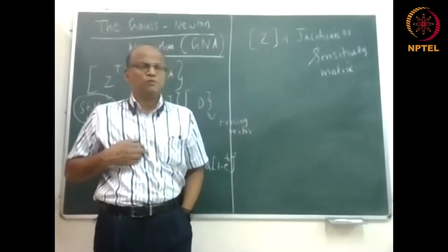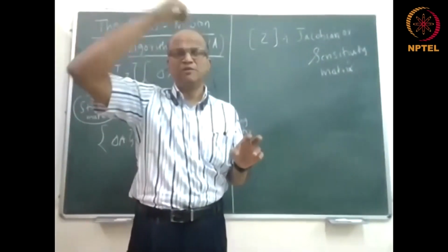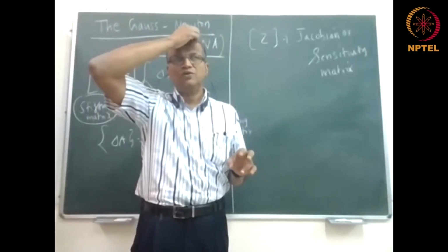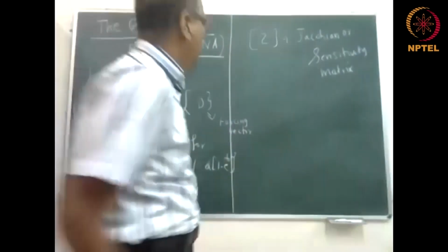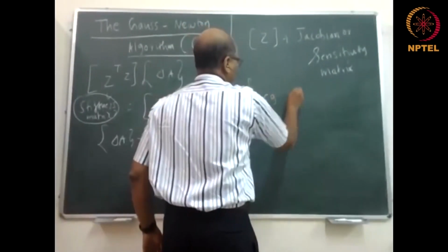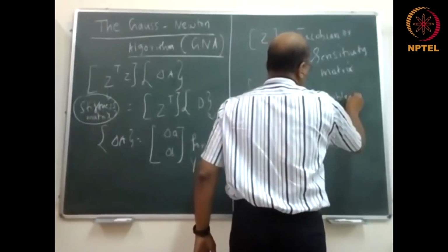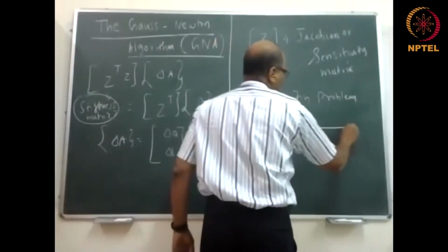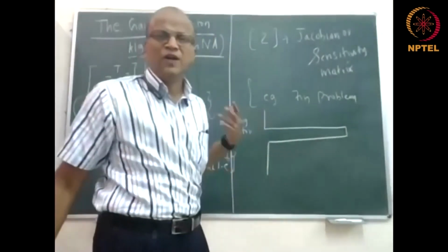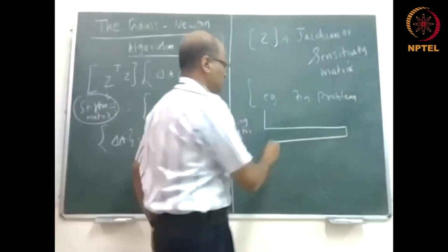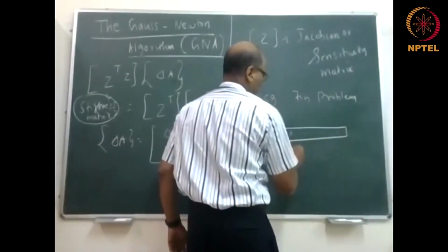Okay, so this could be because the heating is taking place at one place in the problem and you're measuring the temperature at some other place and so on. So you could be putting both thermocouples in the wrong place. For example, let's say a fin problem. Let's say you're using a fin in the heat transfer lab to solve it as an inverse problem to get an estimate of the convective heat transfer coefficient. Let's say that you are measuring some temperatures here, T1, T2, and Tn.